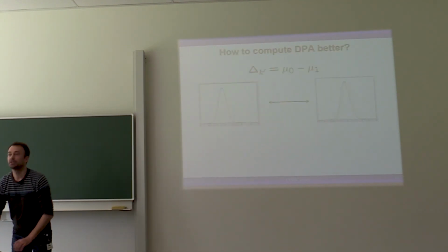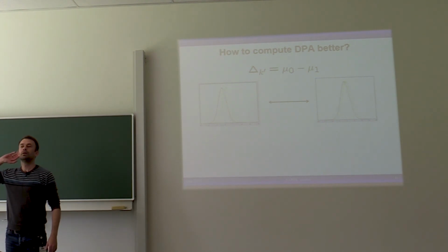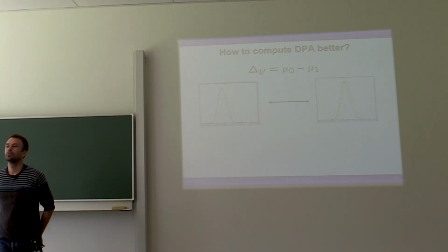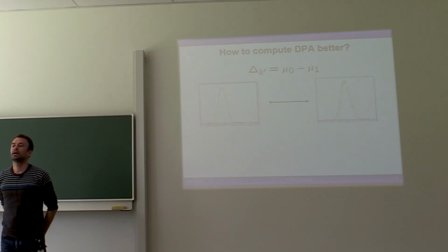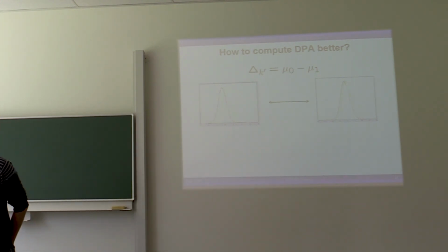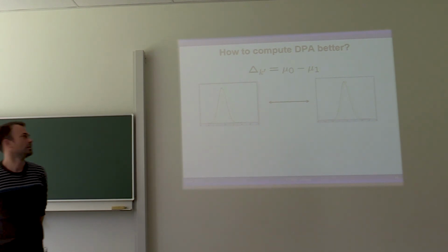One question. Some boards already have protection, like adding random noise on the chip. So does adding more measurements help to find the differential statistic, so we can still recover the key, if the board already has protection by adding random noise on the chip? Yes.